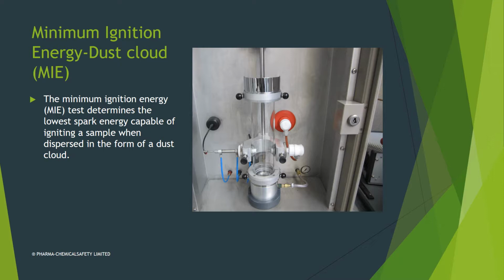The minimum ignition energy test is going to determine the lowest spark energy capable of igniting a sample when dispersed in the form of a dust cloud. And then, like I said, it's used to have a better understanding of the vulnerability of powders and dust to electrostatic discharge.